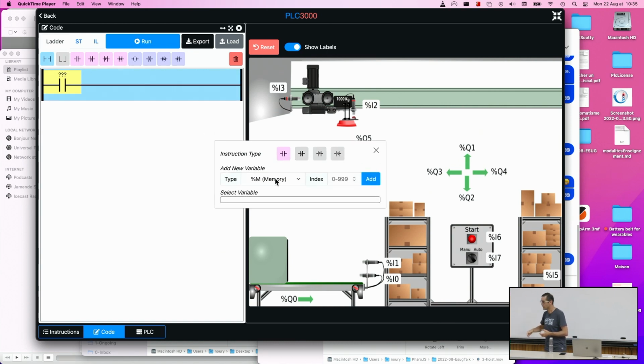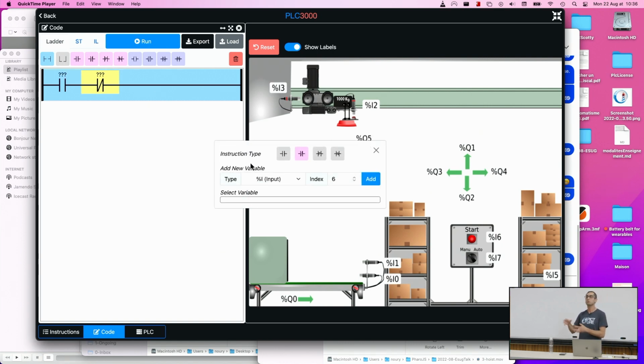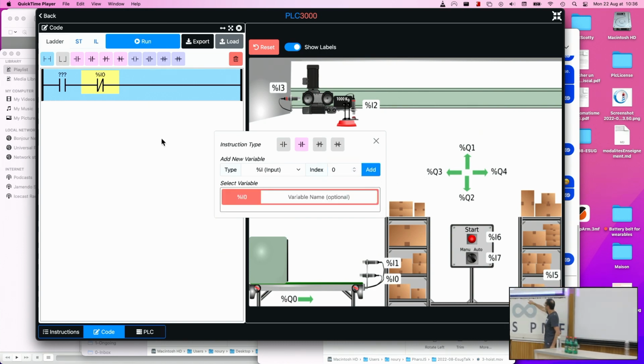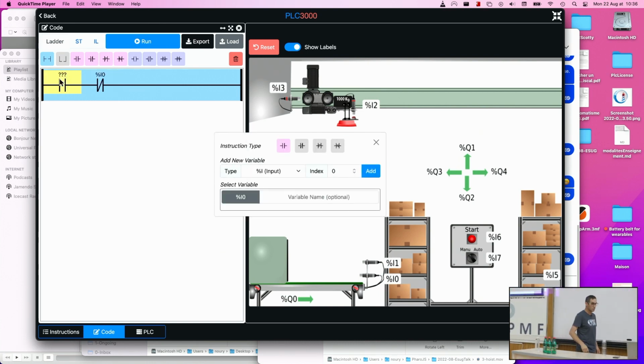Here it's a factory with a hoist, with some parcels, some products, and we need to carry them around. The students will try to write the right program to do what is expected in the exercise, like reading some inputs from a sensor down here and seeing if there is something there. If not, trigger the engine; the output is called Q0.